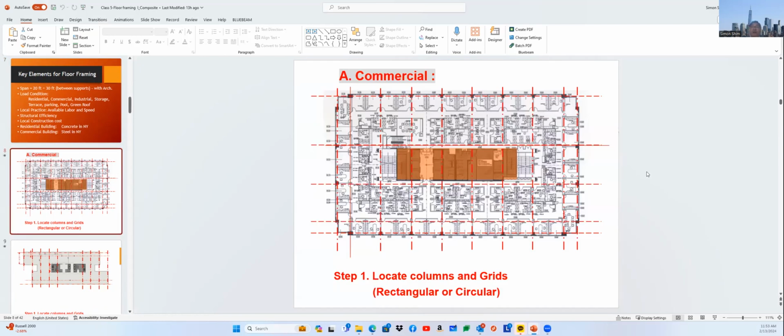So here you could see one example of an architectural interior layout. I drew the red dotted dash lines representing the column grid. It depends on the building's overall footprint, but it should be slightly adjusted. But you could see the major columns on plan north. Let me just annotate. Yep. So this is column spacing. I'm talking about column spacing, typically 30 feet.